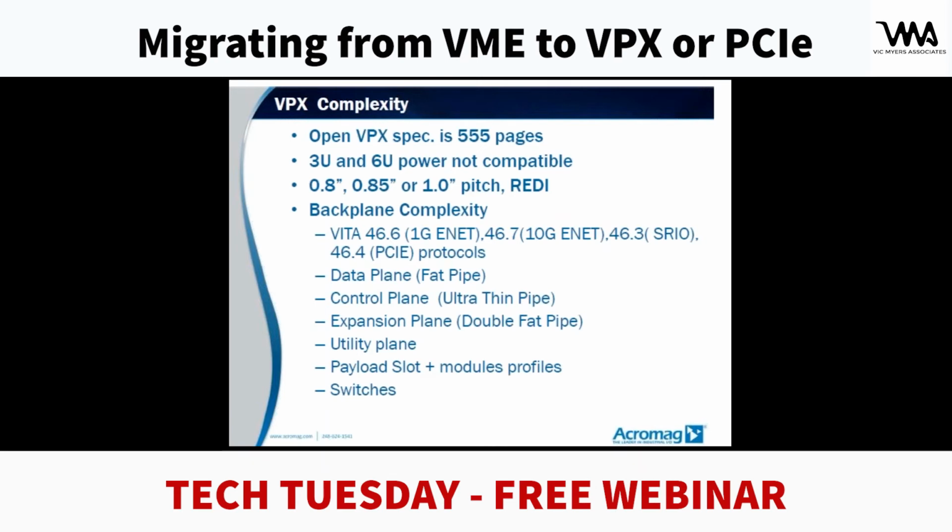Talking about complexity, VPX spec is over 500 pages long. So it takes a lot to understand the technology. And when you look at the 3U VPX and 6U VPX, power supplies are not compatible. You look at the pitches on the different 3U boards and 6U boards, and you have 0.8-inch pitch, 0.85, 1-inch pitch. You have what they call READY, which is Rugged Enhanced Design Implementation for 3U VPX. There's so many different options and choices that need to be made.